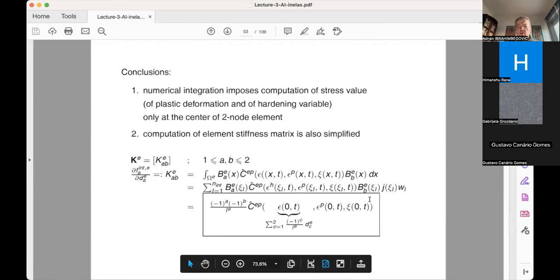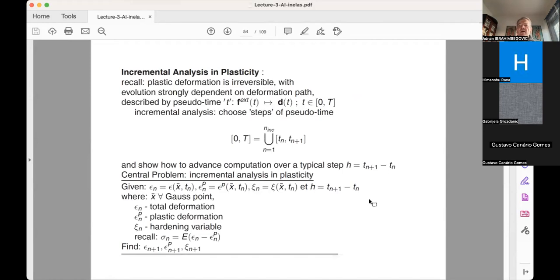So we carried out this computation saying that we have a single step scheme that we already studied for a heat transfer problem, which is simpler because there's no constraint evolution. Here, the main difficulty, we do have a constraint evolution in the sense that the stress should be plastically admissible. Namely, the yield criterion should be always either negative value or 0 value. It can never be positive value. This is simply not admissible.